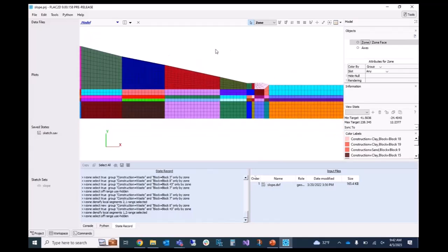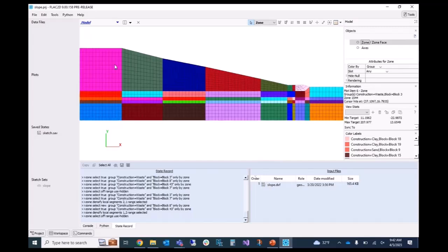The ability to go in here, well, assuming that there's no bug, the ability to go in here and densify things is super handy. And actually, 99% of the time, people are densifying the same in the X and the Y direction, which is probably why no one discovered this bug yet. Because normally what you're doing is saying, oh, I've got a tunnel. I want more dense zones in here. Just take every zone and split it into 4 and go 2 by 2 or 4 by 4 or whatever. And so it's relatively rare that people densify more in one direction than the other direction. Which is probably why we haven't found it yet. But, well, we found it. We just haven't fixed it yet.